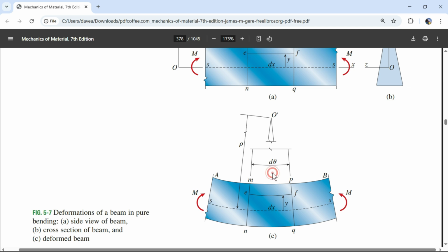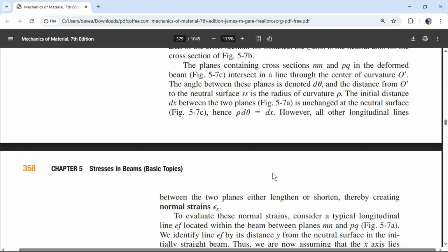There's no reason not to go over that every single time, because this equation comes up so often, and I just think it's visually difficult to see. So I use the axiom: this is the radius, and this is the radians. Radians times radius is something normal, that's arc length. Because when we work in dynamics, we get radians per second. That's going to be the letter omega. And radians per second times radius gives me tangential velocity, something normal.